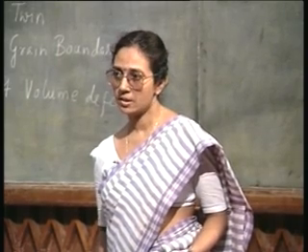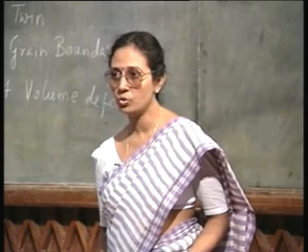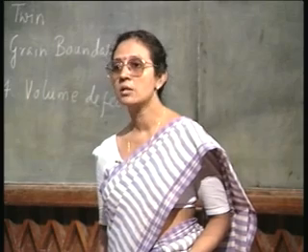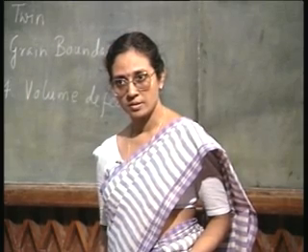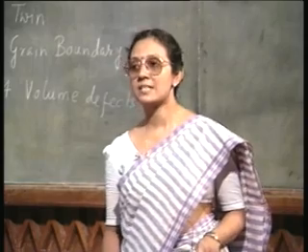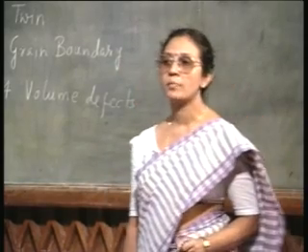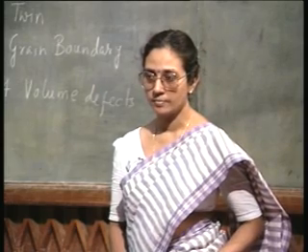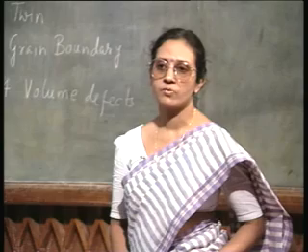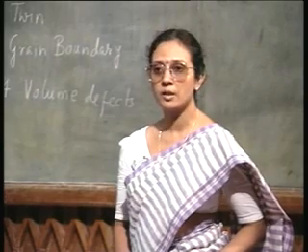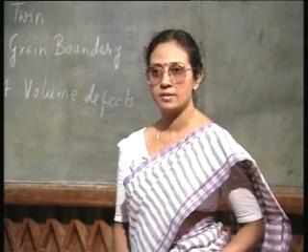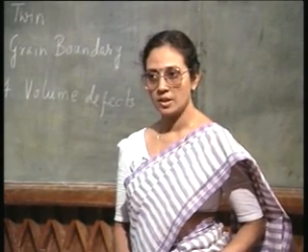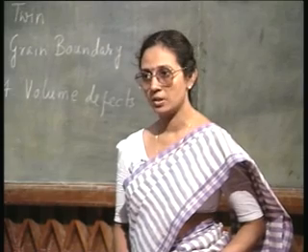But then as the crystal is formed and then finally it is cooled to room temperature, the solubility of these impurities will decrease, and therefore this extra material will be precipitated inside the crystal. They can get precipitated in various forms. For example, if you have metallic impurities, it can form a silicide, titanium silicide or tungsten silicide. It can form silicides and get precipitated.